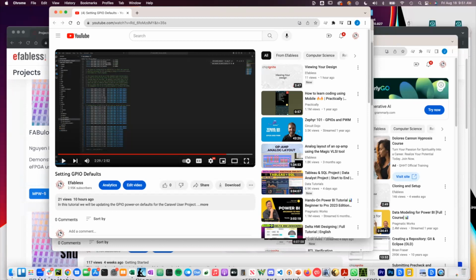So three things: you've got to get the RTL, you've got to define the power connectivity, which is default unless you're doing something unusual. You've got to do the user IO config, and you've got to hook up the OEBs. Yeah, definitely hook up the OEBs. So the RTL, the user IO config with the power supply, and the OEB connectivity. With that basic information, you should be able to get the flow to run. Okay.